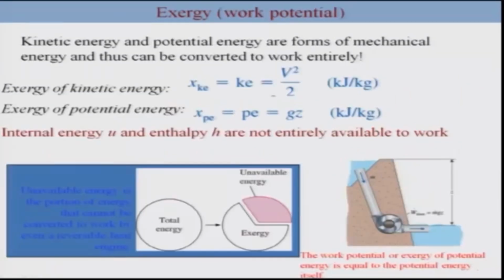So let us continue and ask the question: what about the exergy of, let us say, kinetic energy or potential energy, which are the forms of mechanical energy? As we know from our past exercises, kinetic energy and potential energy can be converted to work entirely, and thus the exergy of kinetic energy is simply the kinetic energy, and the exergy of potential energy is simply the potential energy.